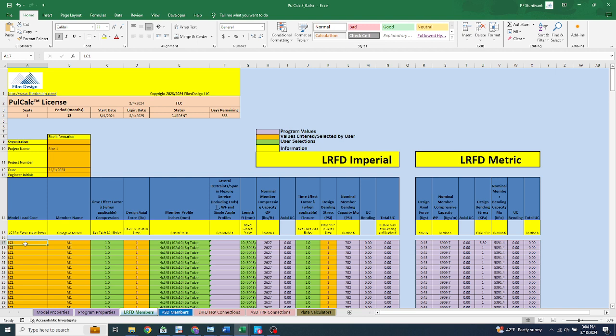When you go to the detail page in RISA and you run the model, and assuming it runs all right and all goes well, you go to the detail page and there's going to be typically a worst case scenario for a load case for maximum bending stress on a member, and also maximum compression forces on a member. So this is where you enter the data here.